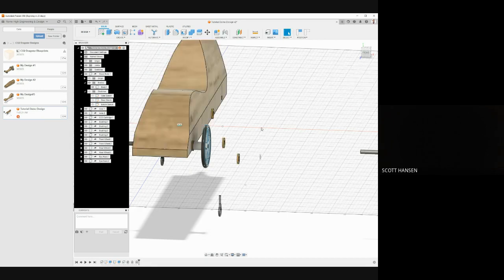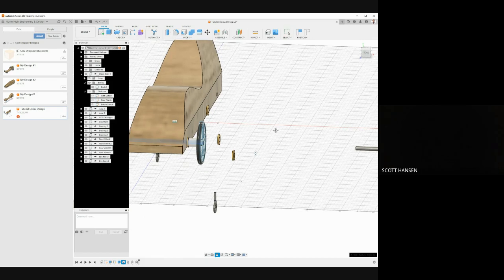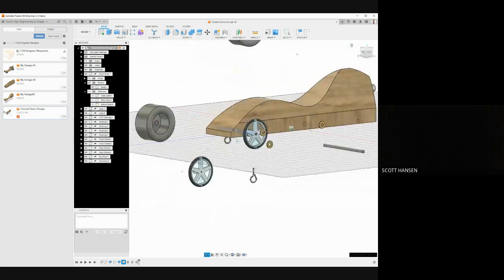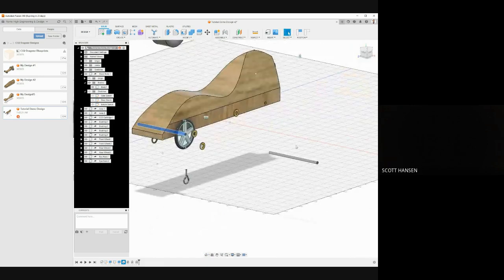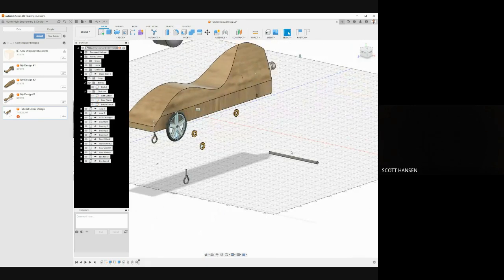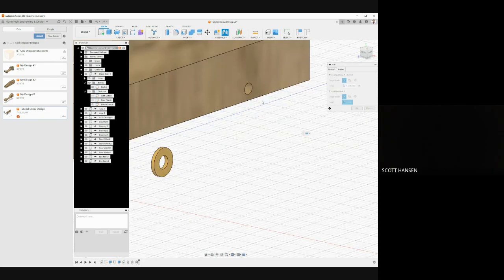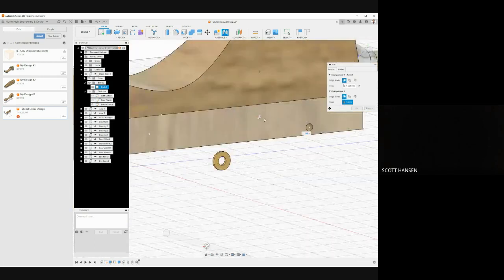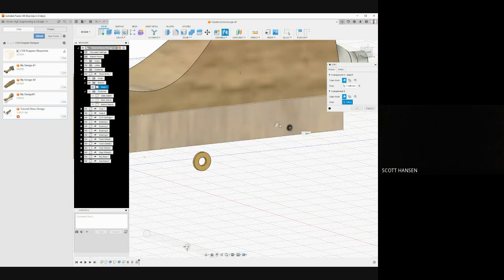All right, that's rigid. And with that particular motion, now we have two things attached to the axle, and the axle itself can rotate inside the body of the car. Now, looks like with the rear wheel, though, this axle is not where it needs to be. So for my assemble, I will need to use my joint tool, which will let me select mate connector points and move parts so that it aligns those mate connector points.